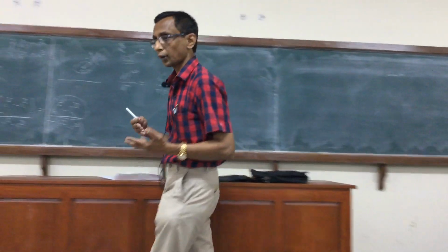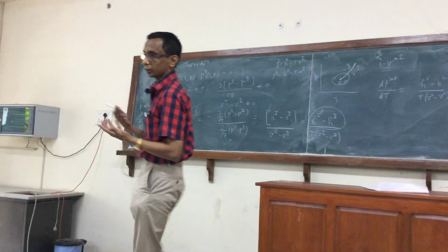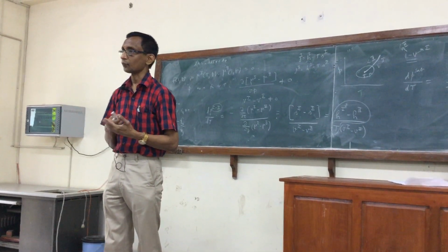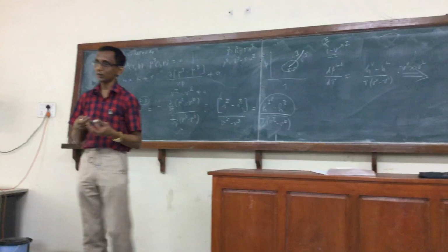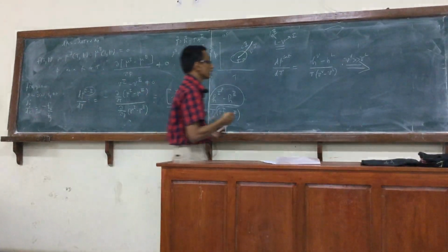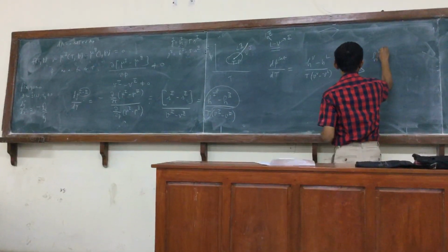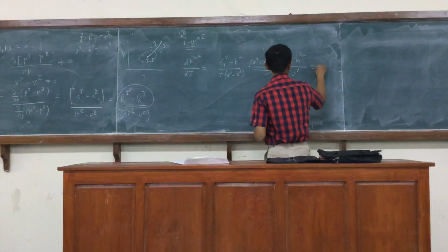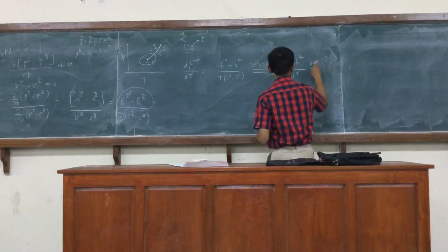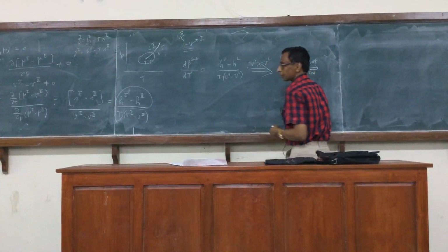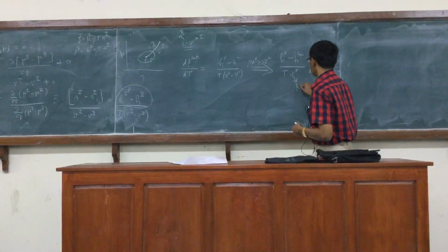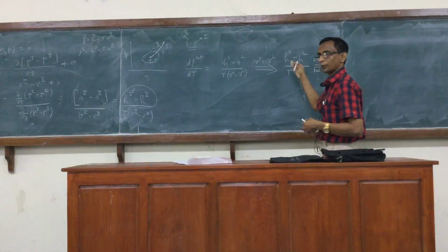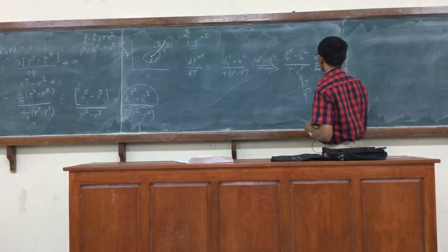assumed to a good approximation to behave like what? At low pressures, ideal gas. So what can I replace the Vv by? So first, I get Hv minus HL by T Vv, and further, at sufficiently low pressure, I can actually replace the Vv by RT by P. The P here is P sat because I am all along the saturation pressure curve.